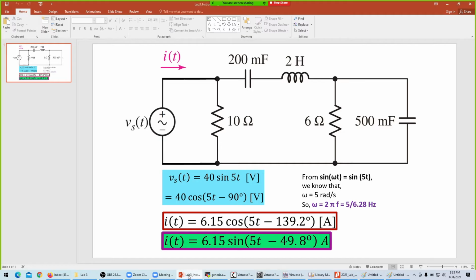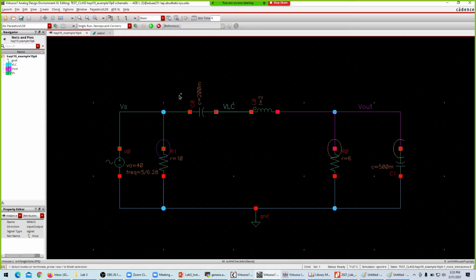one word of precaution. As we see that the current is going from the device to the circuit, right? Remember in the first, second lab instructions, I told you that we can select the current by selecting any of these two outer nodes of a component, and the direction of the current is always towards the component. So if I use the top edge, then the direction of the current will be towards the component. So it will be down.